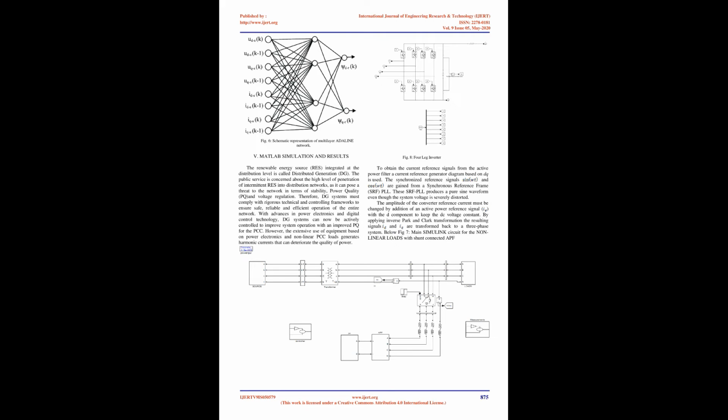Fig 3 shows the principle of this extraction filter. Fig 3, low-pass filter with feed-forward. After the separation, the harmonic components of the load currents are obtained using the inverse of equation 3.6, which provides. In the case of reactive power compensation, it is sufficient to send the reactive power, q(t), directly to the reference current calculation block without using an extraction filter. Fig 4, Principle of Instantaneous Active and Reactive Power Theory.